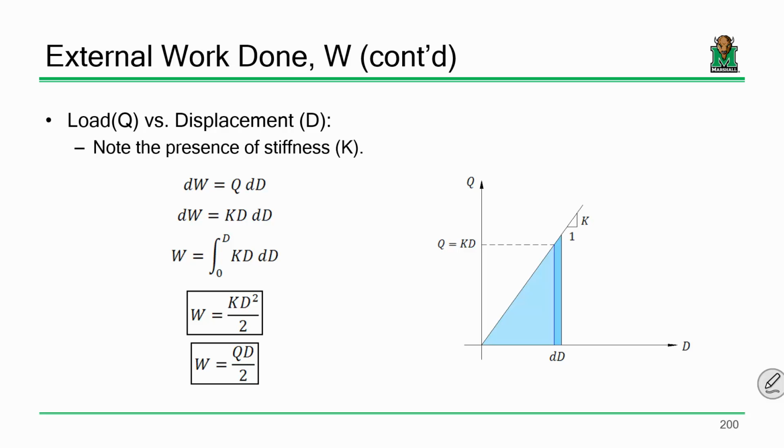All right. So, going back to this problem, we recognize that there is a relationship between force and displacement, and that relationship is stiffness. I want to look at this from an energy perspective. If I plot the relationship of force and displacement, up until now we're assuming that's a linear trend, right? We apply more load, we get more displacement. There is a slope, a relationship between force and displacement, and we call that stiffness, right?